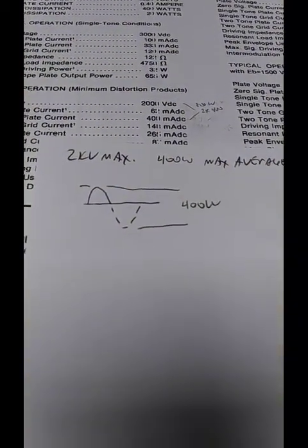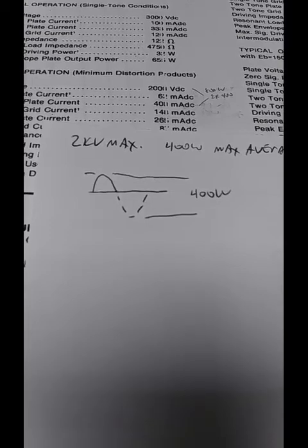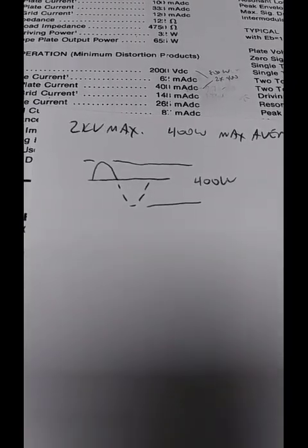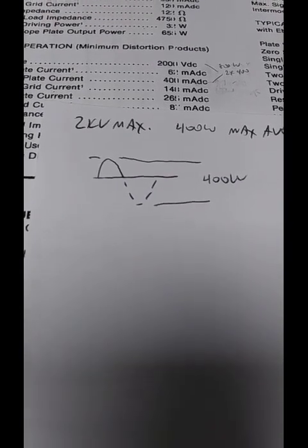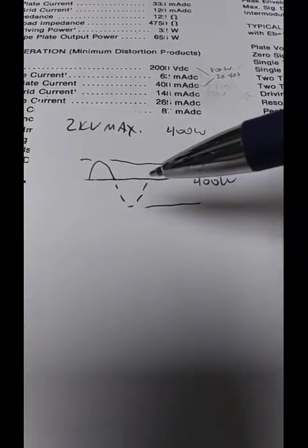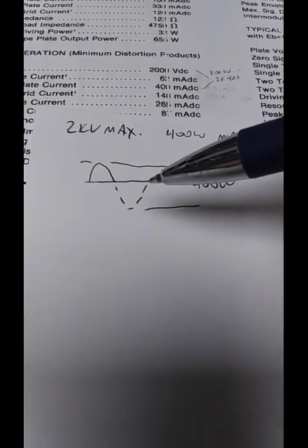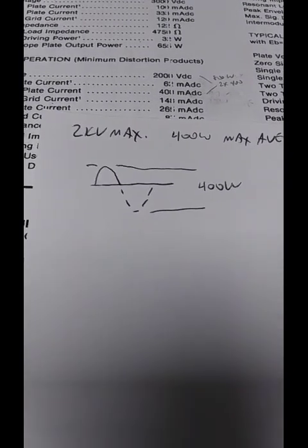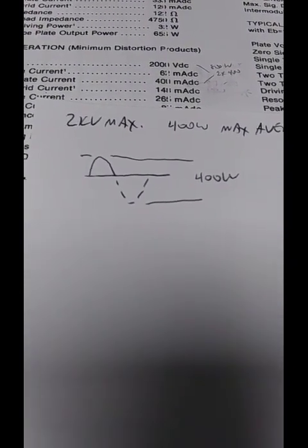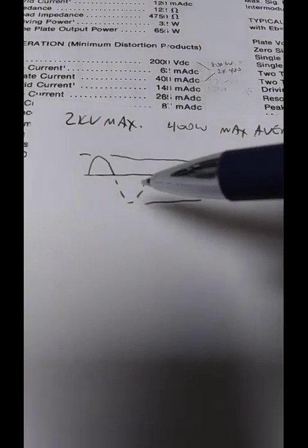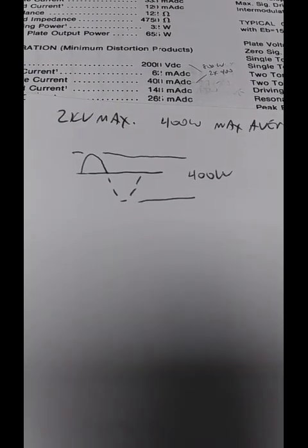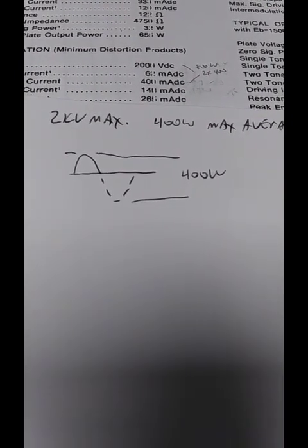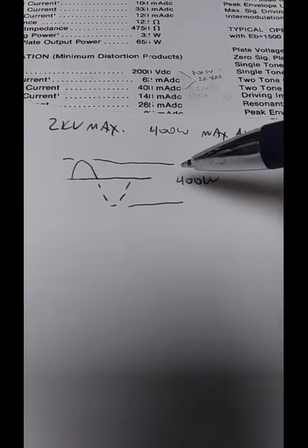Over an individual operating cycle, which you can find by taking the frequency and inverting it, that gives time per cycle. If it's a million cycles per second, then each cycle is the inverse of that, 1 times 10 to the minus 6 seconds. At 80 meters, it's down in the nanosecond range, but this cycle time is very short. So the exact dissipation over that cycle is extremely small, but all those million cycles per second add up over a second to be a max of 400 watts.